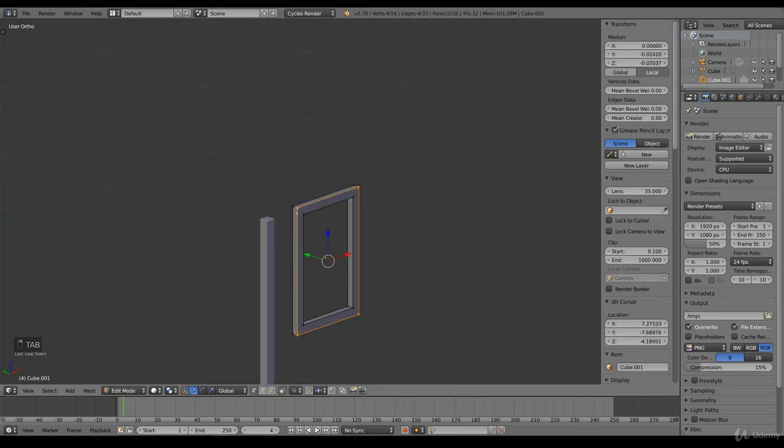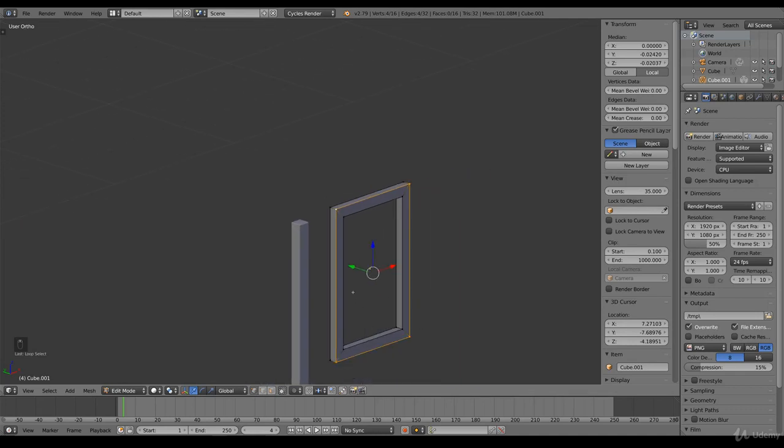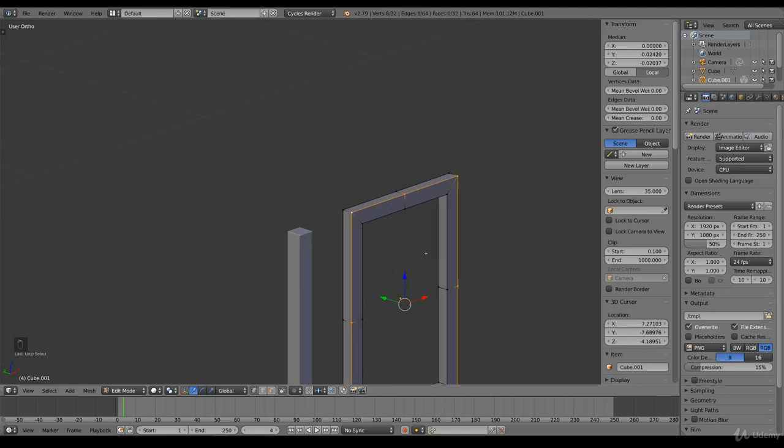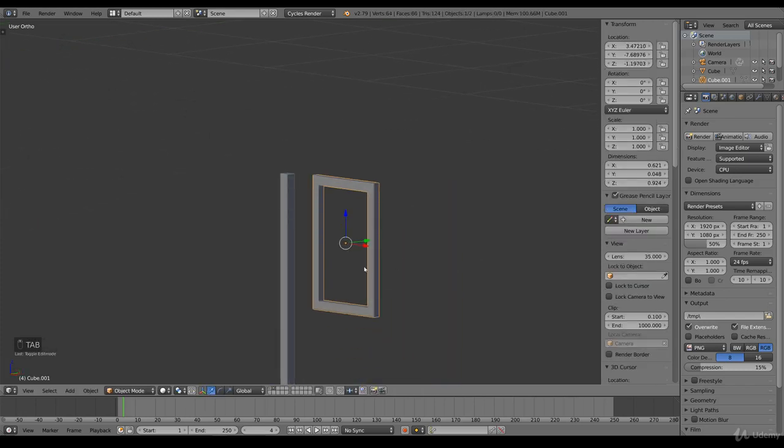So we want to select this line. Oh, before we add the bevel, we add some extra edge lines, so we have more control over the editing process later. Now we Alt right-click on the outer edge loop vertices, Control B, and add this bevel. Very smooth but visible.